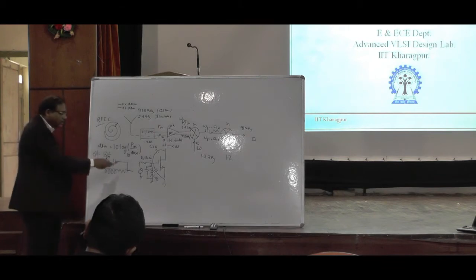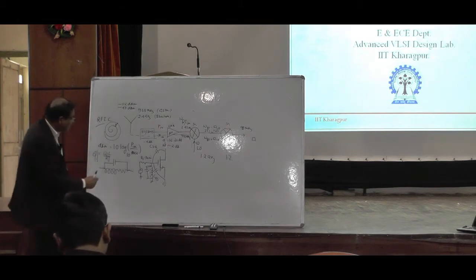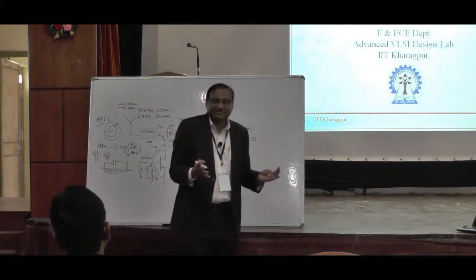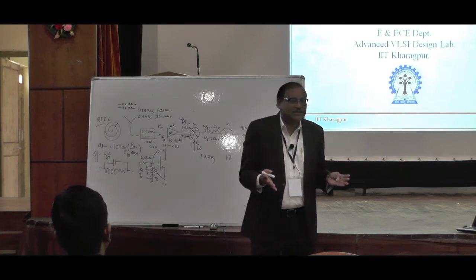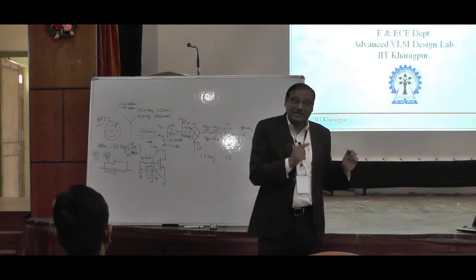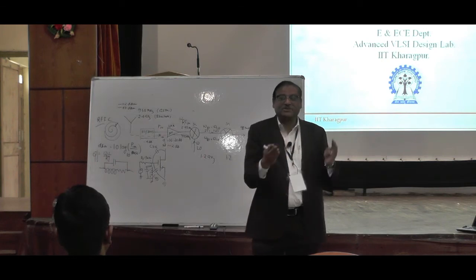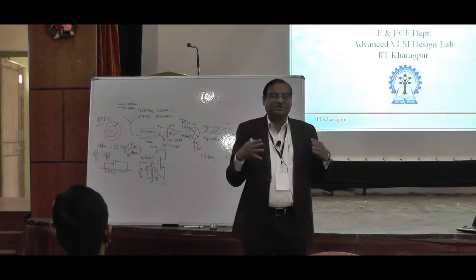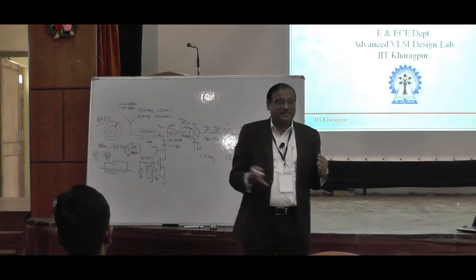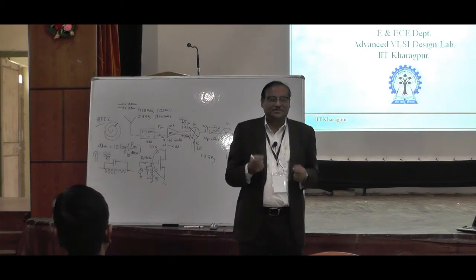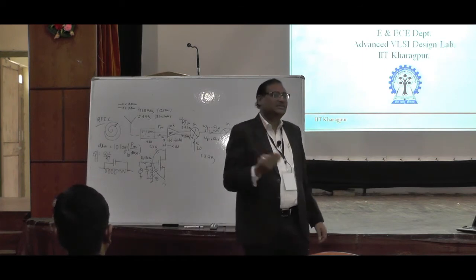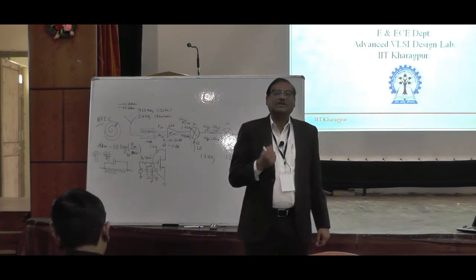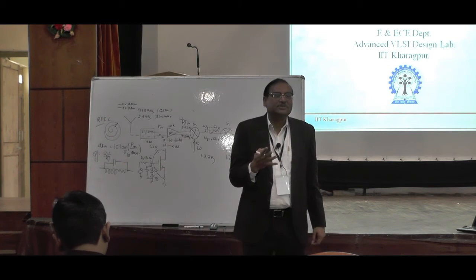Yes. Then who will negate that capacitance? Again, this capacitance will be added to my CGS. So it is an egg and chicken problem. To negate that capacitance, again you have to put one inductor. The inductor would have a parasitic capacitance that will be added to your CGS. So this is not an equation which is going to converge. You need some kind of optimizations. So that is the challenging task. You need iterations, very long iterations, but finally you are getting maximum power transformation.